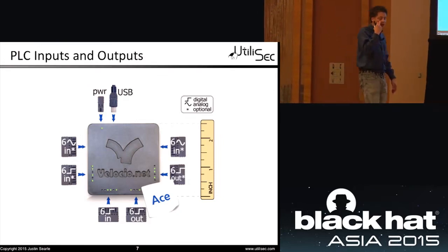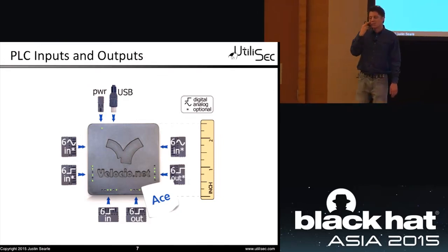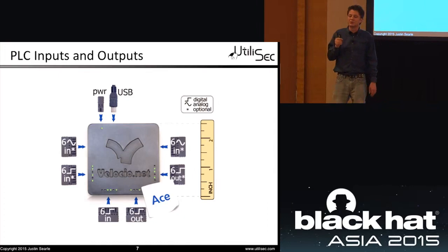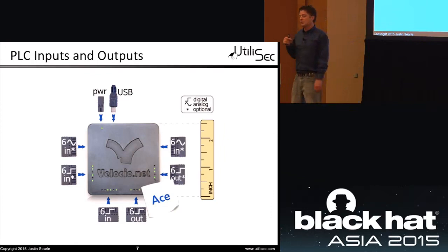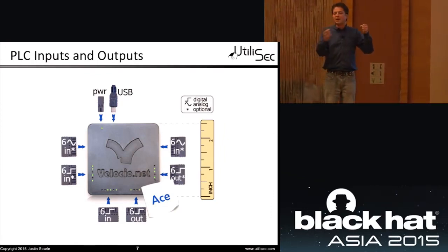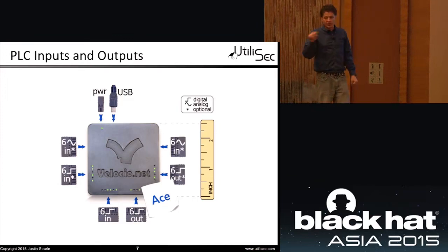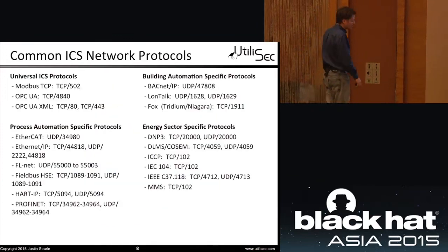When we are going through and using a protocol like Modbus, Modbus is a simple protocol that allows us to say, read this input or change this output. And that's all Modbus does. Very, very simple protocol. Modbus has to be communicated from the master down to that PLC unit. It just says change or read or write is really all that we're doing with Modbus.